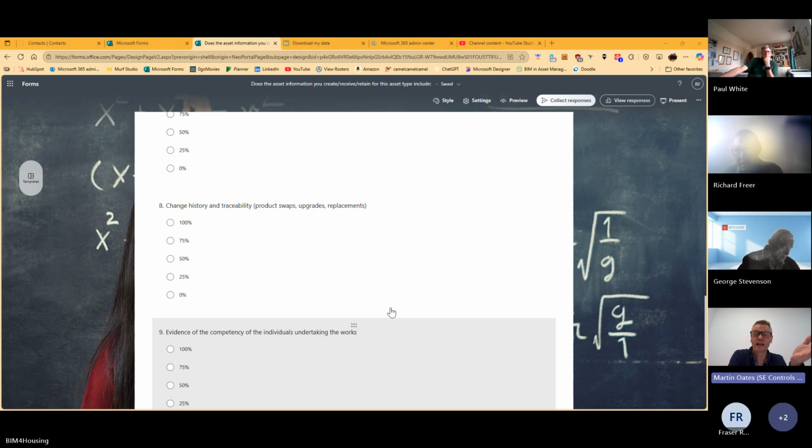So, for instance, if you look at AOV, that's EN 12101 Part 2, and it's certified with a CE mark and a DoP to declare its performance and place it on the market with the notified body's reference on there. That's subject to a third-party auditing process to complete that product, but that information of who that was and their competency doesn't sit behind that documentation to certify it and place it on the market.